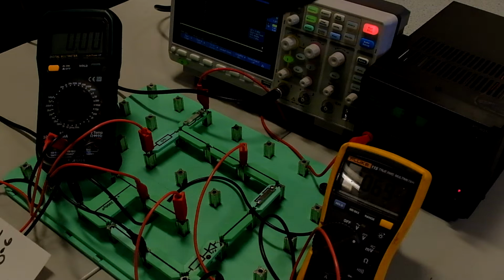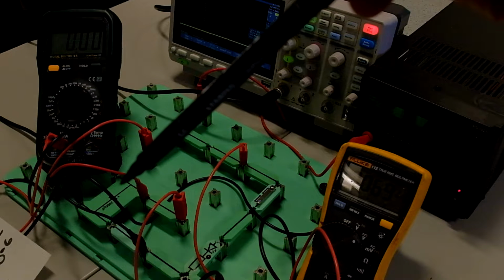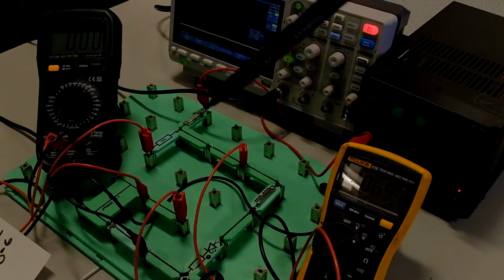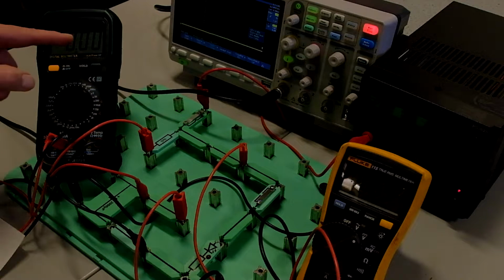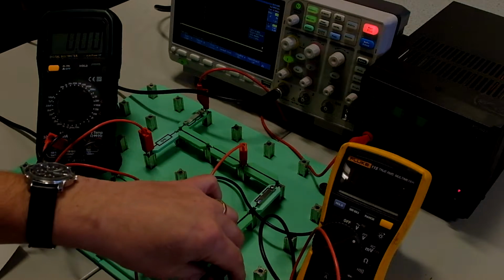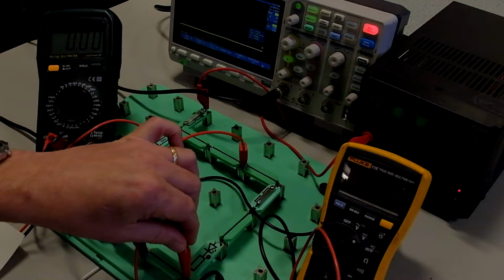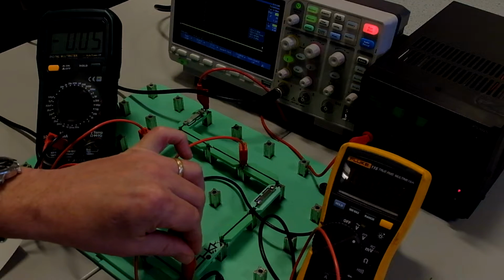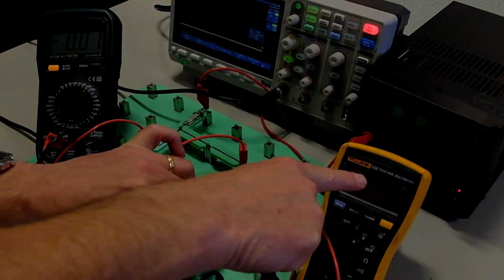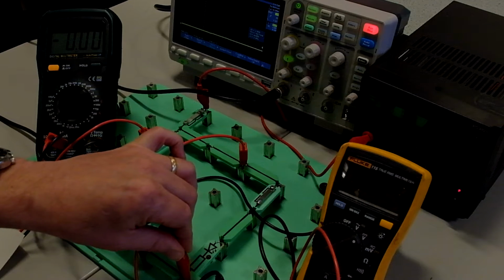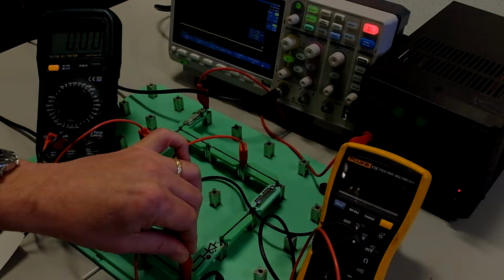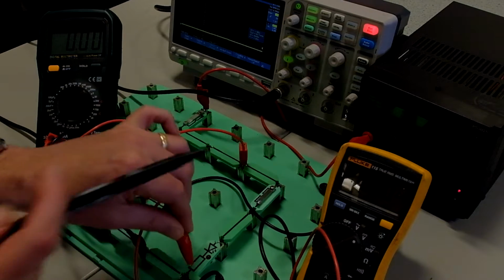On the electronic box, we have a 1K resistor, a 2000 microfarad capacitor, a simple mechanical on switch, current and voltage readings, and a digital scope. Current is 0, voltage is 0. We're going to make sure it is discharged properly. We can see the voltage coming down right down to 0 volts across the capacitor. We're making sure it's fully discharged. Voltage has gone down to 0.